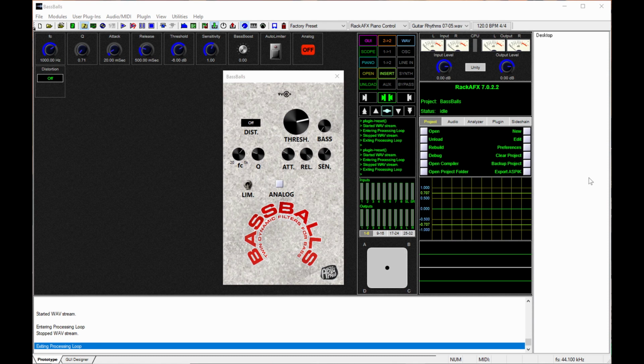When the Q is set to 9.8, you can hear the slight oscillation, but it won't fully turn into a sine wave. In the original Moog synthesizer, the nonlinearity of the hardware works as a soft limiter and tames the output down. In this plugin, it is replaced by an optional hard limiter here.